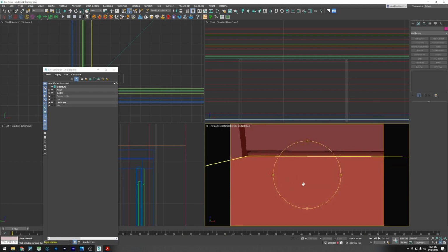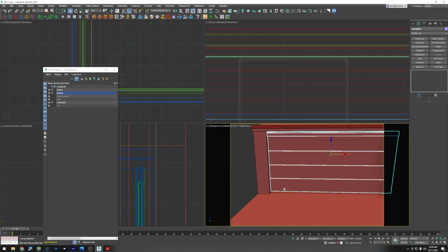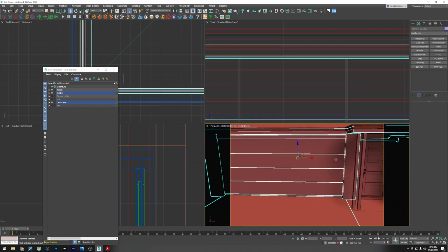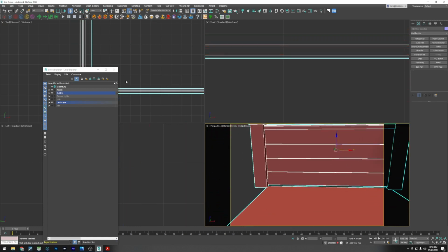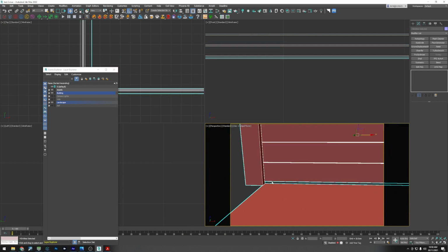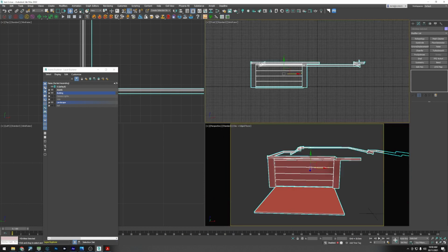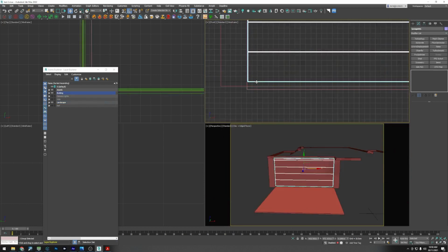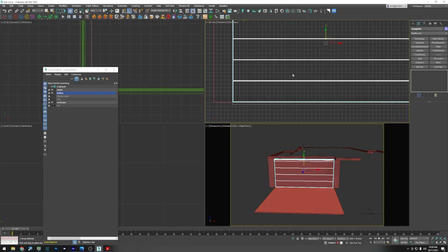The garage door there, you can see actually looks a little bit low. So I might need to just go in and adjust that. So I'm just going to select those two walls so I can see what height we're supposed to be at. You can see there's a really big gap there. That looks silly when we try and render it. So all really important to try and make sure that's at the right height. So we're going to bring that down a bit.